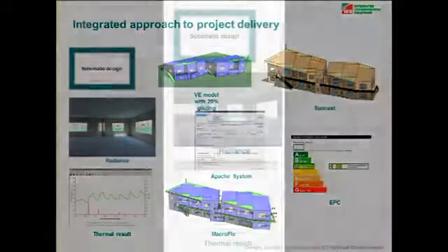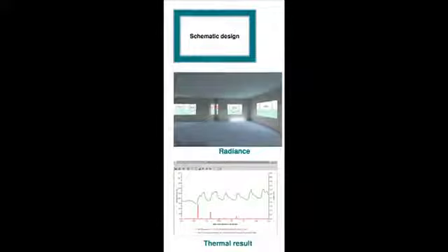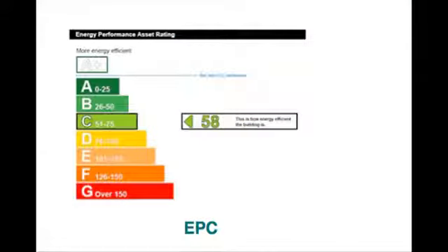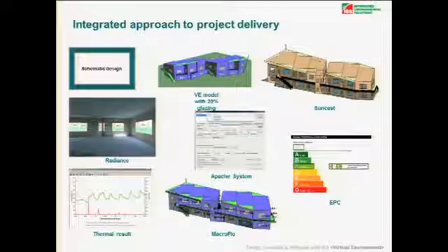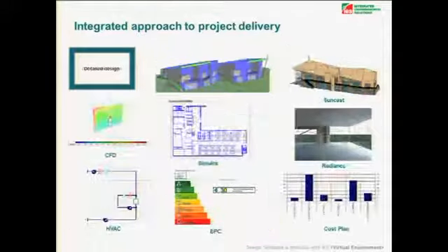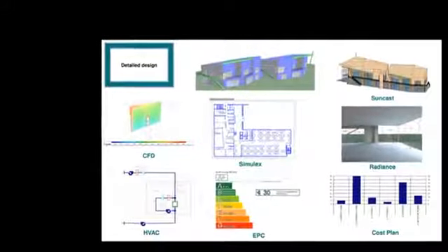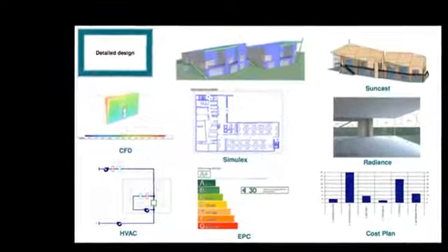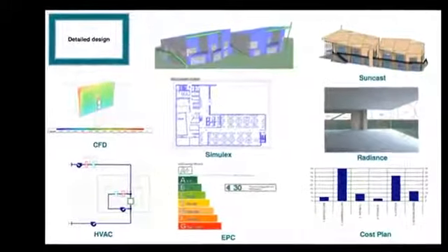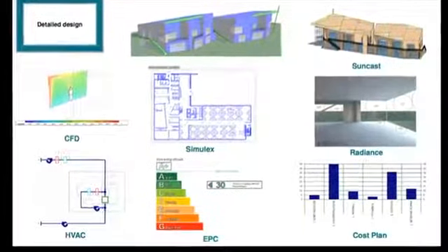Into schematic design, we might have a preferred option. We can start to look at compliance, so UK compliance with Part L, EPCs, again BREEAM, or if it was elsewhere, we could be starting to get some early feedback on LEED performance as well from the earlier stages. Again, refining the data, so integrated feedback on the glazing configuration, for example. That will give us feedback on energy, daylighting, any glare issues that we might get. We can look at all of those things within the software. And then in detailed design, really what we're talking about here is a submission quality model, okay? So the model that we're going to be using with all of the detail refined in it, that would then be submitted as part of your BREEAM certification or producing your Part L document, for example.